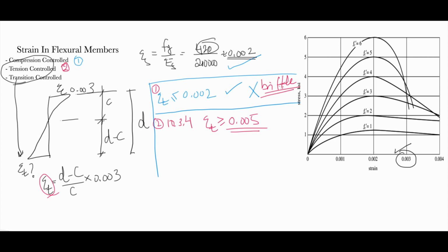Why is that? Just go back to the first point, number 1. Imagine that I have a beam and I filled it with steel. It is so filled with steel that the steel doesn't even have the chance to move or bend. What does that mean? That means the beam fails before even the steel felt that there's a problem. So the concrete is crushed and it falls totally, because I filled the beam with steel.